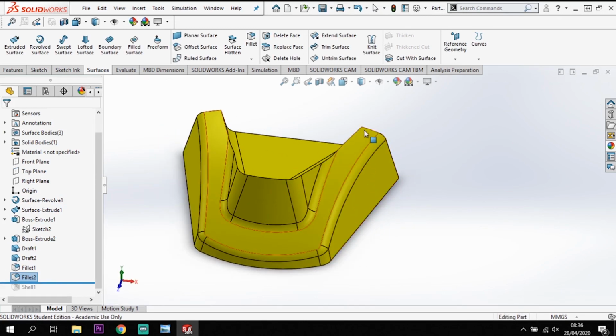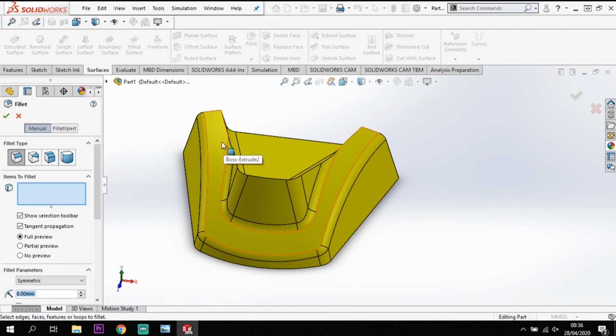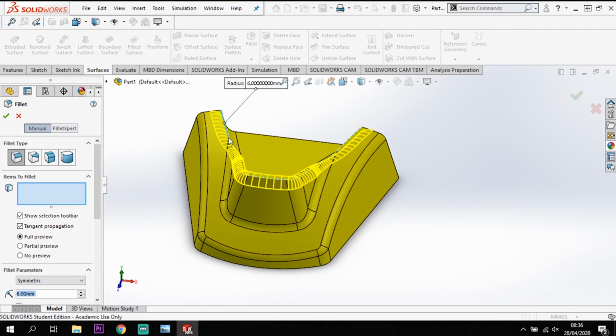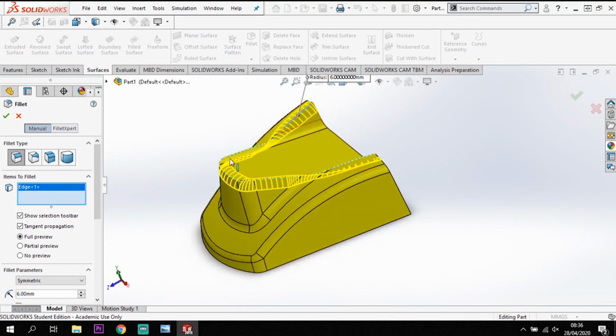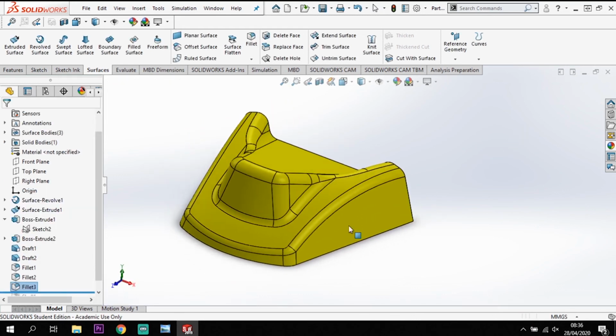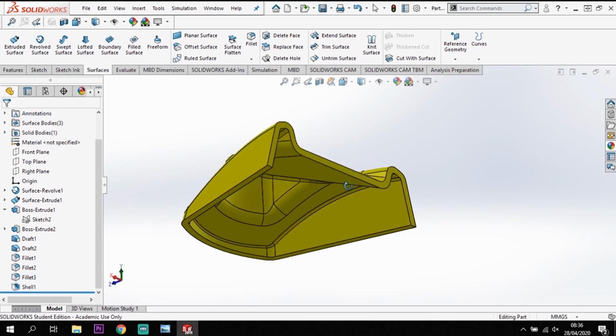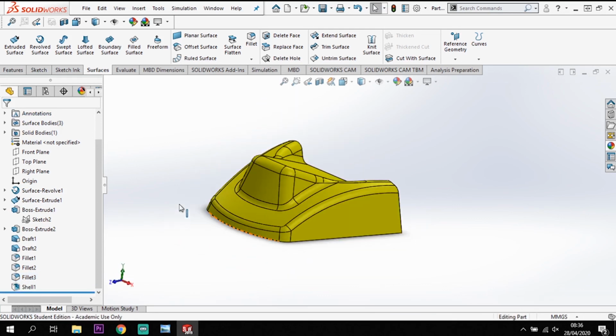We're just going to put a final fillet in to pull it finally into place. So fillet tool here. And I'm going to take that 6 milli fillet around this top edge here, all the way around, and that will close off that top edge with that fillet. Take that in place, and we finish off with that shape that we are after. Okay, last bit then is just to drop this down to complete our shell. It will now shell out the inside of that, and we are looking exactly how we want it to be.